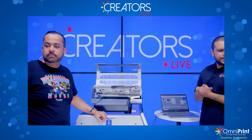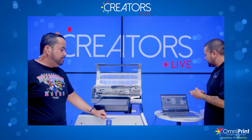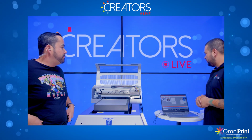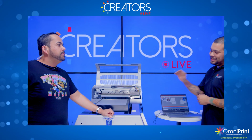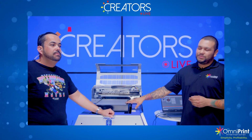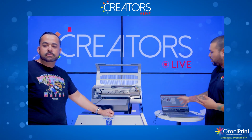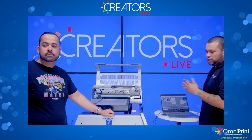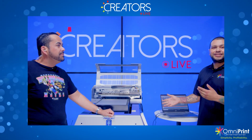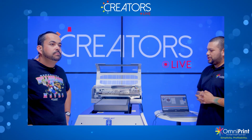As far as the supplies, we'll go over a little bit of the RIP software settings we're going to be using. We already have the environment for it, so you won't have to sit there and guess. I did test a lot of different films, and some of them worked great, some of them didn't. With some of them, the ink wouldn't dry as fast. These settings partner up great with this film and work perfectly. We don't have to do 2 passes. I think I've heard some customers using 2 different passes of color and of white. We won't have to do any of that. It'll be just like we did for a regular t-shirt.